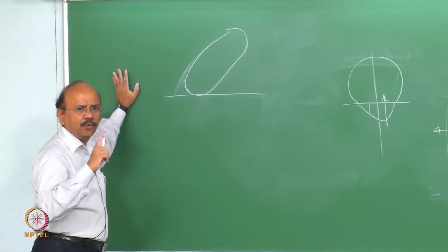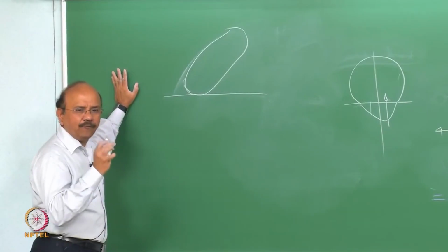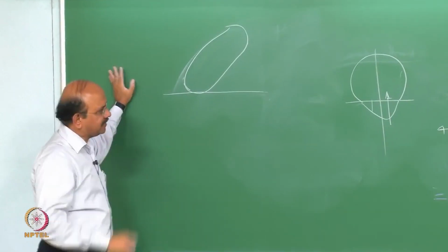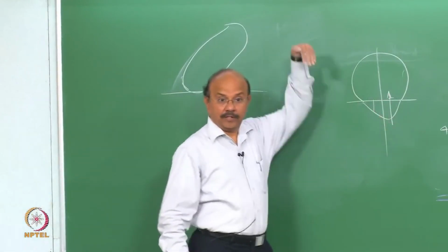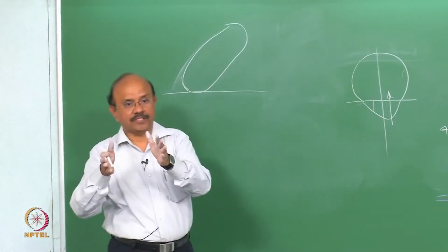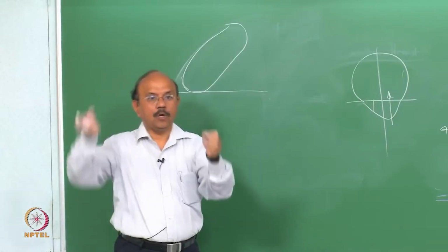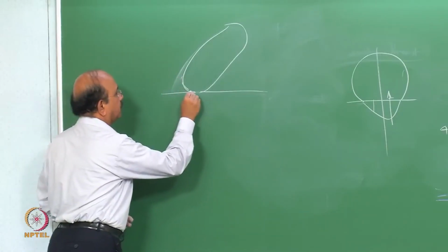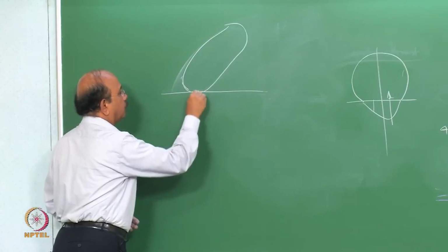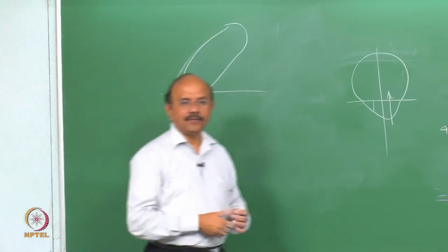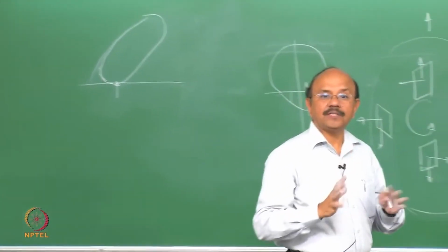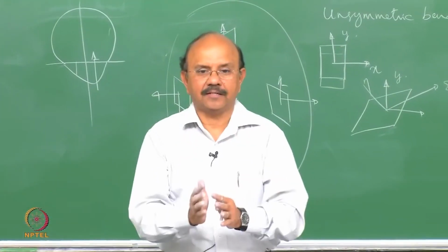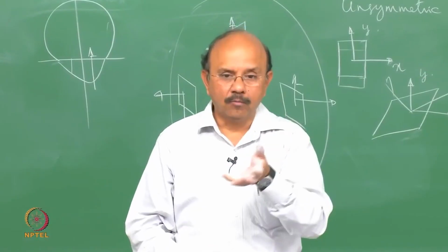But please note that the complete force doesn't act right at the center of the contact patch. If you look at it from the top, it acts to the side, which gives an overturning moment. In the actual case, that gets deformed, and so the force acts like that. So completely resolved forces do not act symmetrically at the center, because of which so many moments are created.